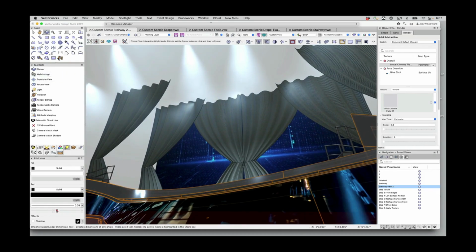And this allows us, with that tool, to select a face, apply to the whole object, or replace a matching texture. So if I had multiple surfaces that all had the same texture, all I had to do was select one of them, and then a pickup and a dropper mode.